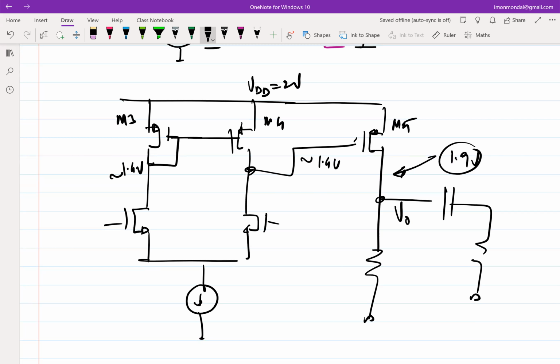So if you bias your circuits in such a way that the voltages on both arms of the difamp are approximately similar, then the arguments of symmetry also hold much better than if the voltages of both arms of the difamp are not identical or not symmetrical, right? So this is a very heuristic way of explaining. This is a slightly advanced concept, but I'll just state it. I'll not go deep into this.